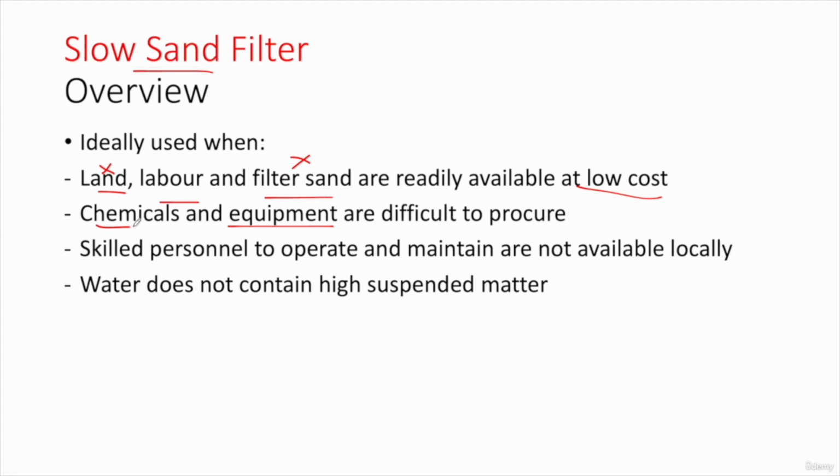Also, slow sand filters are ideal when skilled personnel to operate and maintain are not available locally. A slow sand filter basically needs no expertise for its operation and maintenance. We don't really need skilled engineers and skilled operators, unlike the rapid sand filtration and processes like coagulation and flocculation that involve strict monitoring.